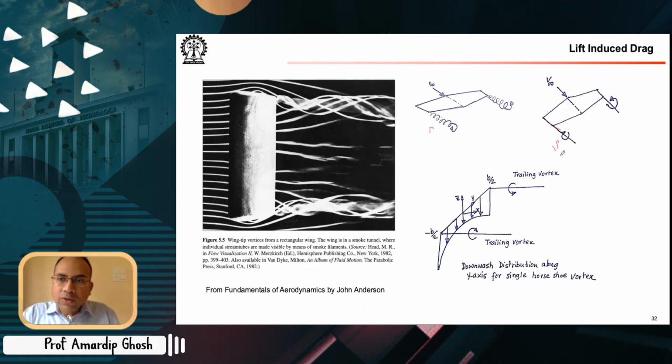Okay, so of course you cannot replace these trailing vortices by this vortex filament just per se, but since we are interested to find the effect of these trailing vortices in terms of the local relative wind, this replacement is justified. So it models the effect of these trailing vortices on modifying the relative wind direction, we will see.